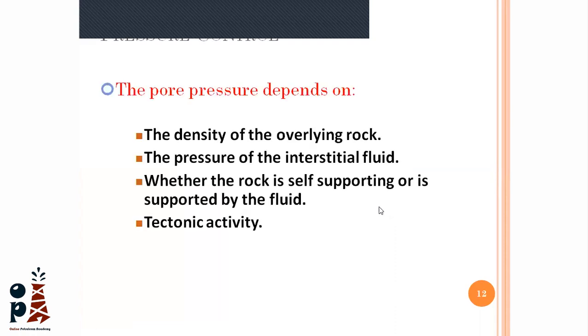What is the pore pressure? You know, guys, our fluid, or gas, or oil, is not down there like a pool of oil. No, it is inside the rocks. The spaces between the rocks contain this oil or gas. If we have a formation at, for example, 3,000 feet or 3,000 meters, there are overlaying rocks from zero depth to 3,000 feet or meters. This overlaying rock will determine the pore pressure, which will be the pressure of the fluid of these rocks.